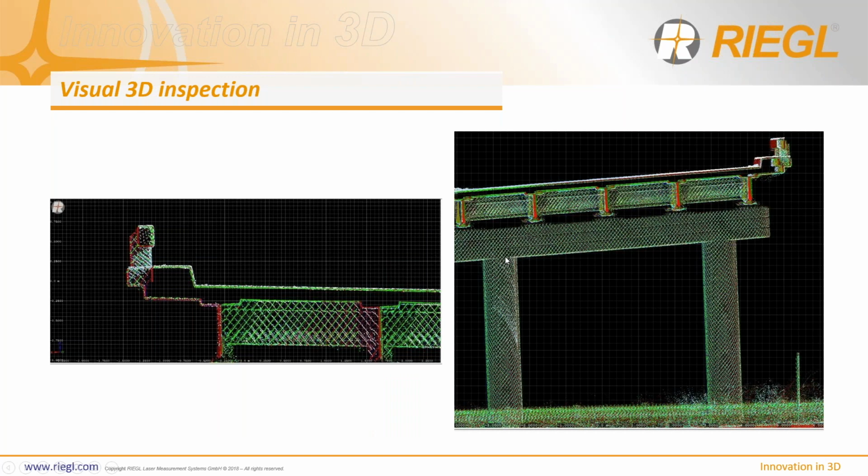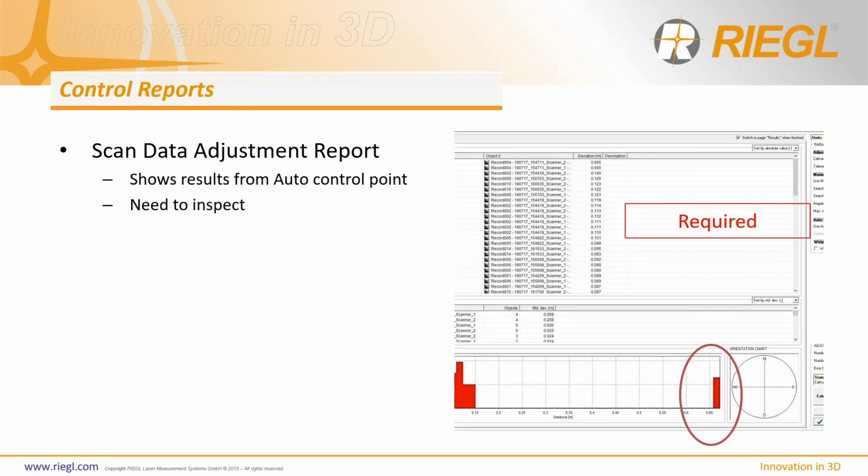Yeah, there we go. So, 3D inspection. Here I took a bunch of 3D cross sections. I zoomed in. I looked at my bridge structure, my curving, how everything fit together. It looks as I would expect from a multi-pass job where the side features here are a little messy and there's some indentations along this sidewall here. That's why you see the shots on the end cap there. That's actually this. There's breaks in the barrier. So you can see it looks pretty good from far away, but as you zoom in, you see more differences and offsets. So then we get into running control reports.